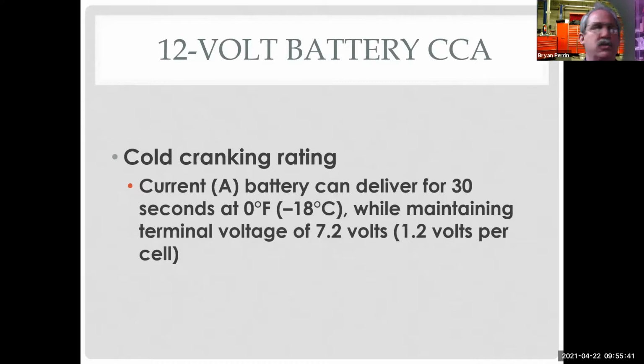Before we get into construction, let's talk about the parts of the battery we're actually buying. So one of the parts on a battery, we know they're all 12 volts. One of the parts I'm buying is its CCA rating. What's the cold cranking amps, right? So what's the strength of the battery? And this is measured at 0 degrees.